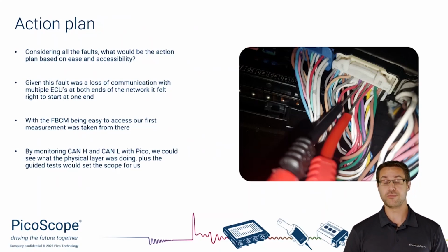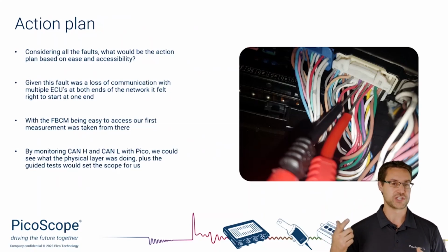When it comes to CAN, one of the most important bits of data that you can get is the network topology. Basically this is an overview, kind of like a bird's eye view of the network in its entirety. So rather than having all different components connected, it's purely looking at the connections between ECUs and where they sit on the network. That can be really helpful with identifying things like end-of-line resistors, which ECUs have the termination resistors in place. And from there you can start to think about, well, where am I going to start to measure in order to try and diagnose this particular fault?